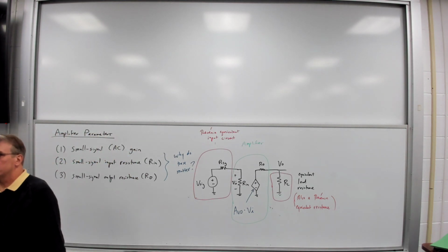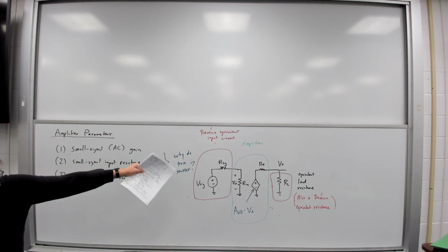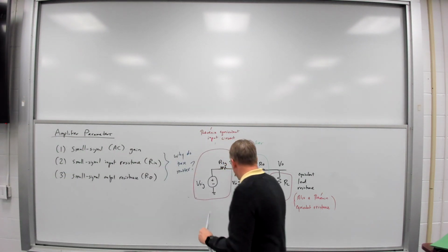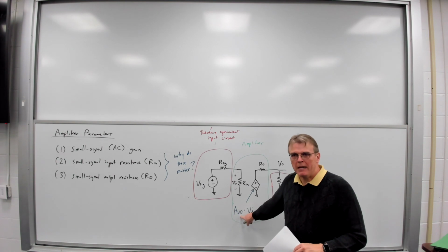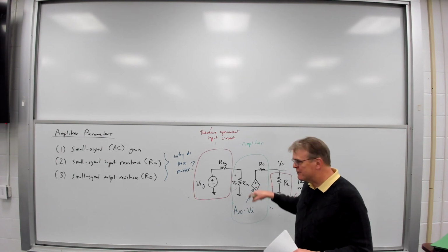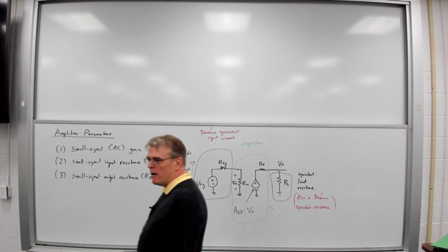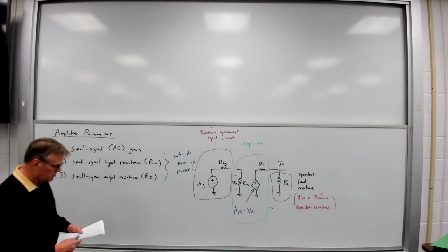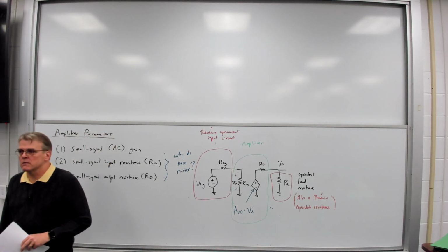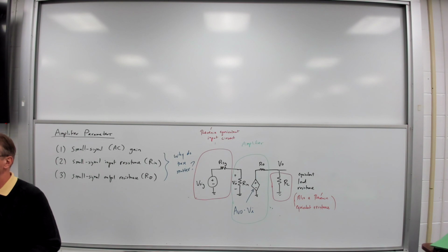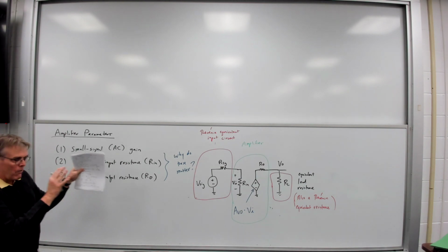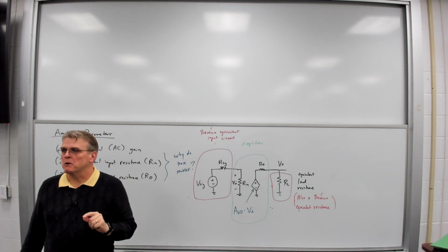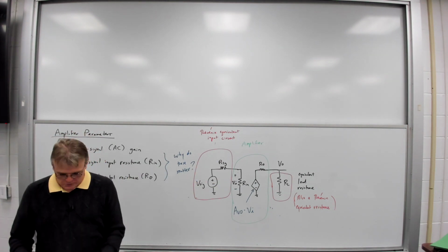Now I drew it this way in order to incorporate the input and output resistances. All right? A_VO is going to model the voltage gain of the circuit, except in this case I'm doing it as a simplified model, a voltage-controlled voltage source. Okay, so questions about this? Everybody see what I've done here, how I've drawn this? Why did I draw it this way? Because now I'm going to take this circuit, do some simple nodal analysis to it, and write myself a few equations.